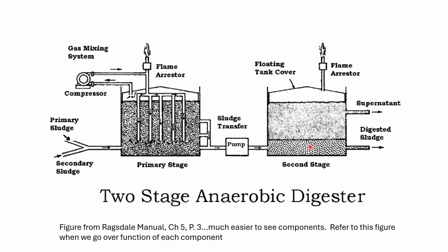So our solids concentration in here is much greater than the sludge we sent from the primary and secondary clarifiers. We're collecting this digested sludge, which has increased in its solids content. That's the beautiful part about it, okay? We have just saved ourselves a whole lot of money by not having to handle wet sludge. It sounds silly, but with the volumes we're dealing with, it makes a huge difference, okay?